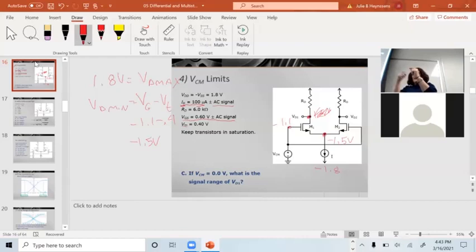Yeah, the output rails, because the op amp itself has this huge gain, like 100,000, a million. 1/10 of a volt times 100,000 is higher than the two signal rails. It's going to rail at one of the power supplies. That's the way you operate an op amp as a comparator: I put a voltage difference on the inputs.